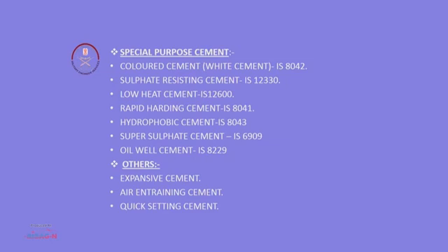The strength of this cement is almost the same as the other cements, but the advantage is that its resistance to frost is higher than normal OPC or PPC cement. Super sulfate cement is also one of the sulfate resistant cements, but it is one grade higher than the normal sulfate resistant cement. And oil well cement,